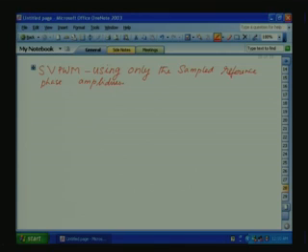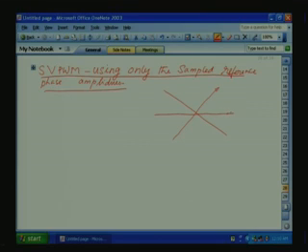Okay. Let us draw our space vector diagram. From a 3-phase system, the periphery is a hexagon. This is our sector 1. So, this is the hexagonal space vector structure. This is 1 0 0, this is 1 1 0, 0 1 0, 0 1 1, opposite to this one 0 0 1, opposite to this one, this is 1 0 1. This is our sector 1, S1, S2, S3, S4, S5, S6.